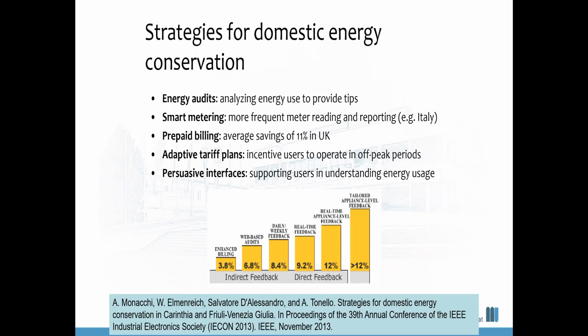They are very difficult to realize without smart meters, because basically you need to somehow register when a certain consumption took place. So either you have 2 meters, where 1 meter is used during daytime, around noon, and the other meter is used in the evening, and probably a third meter would be used at the weekend if you have 3 tariffs. But that would be a lot of effort, and you still need some kind of clocking device to switch.